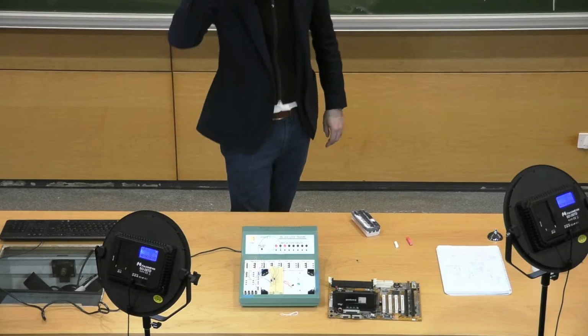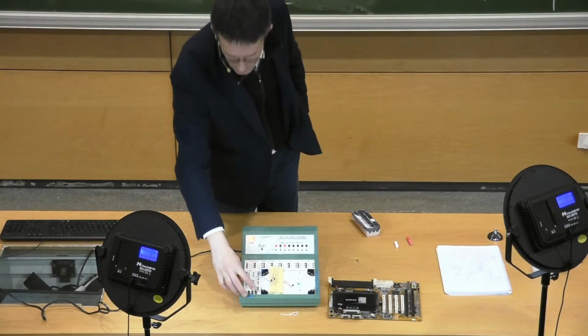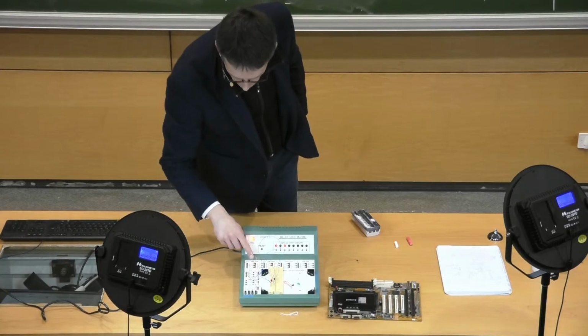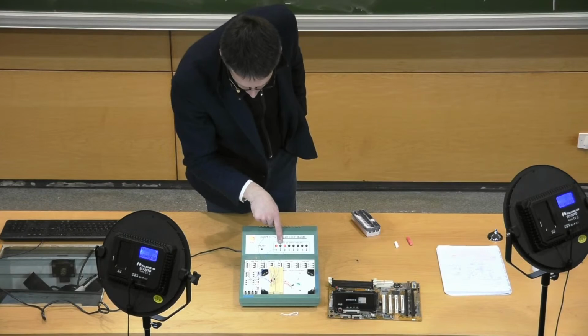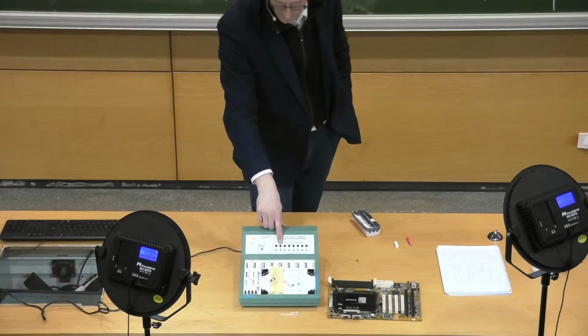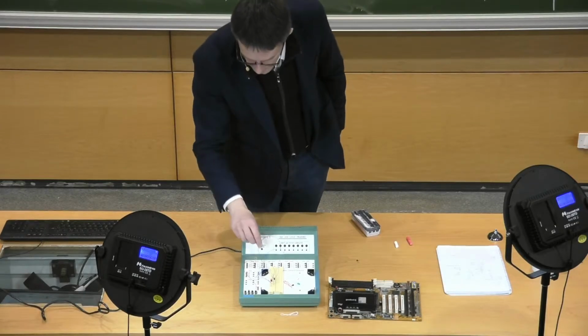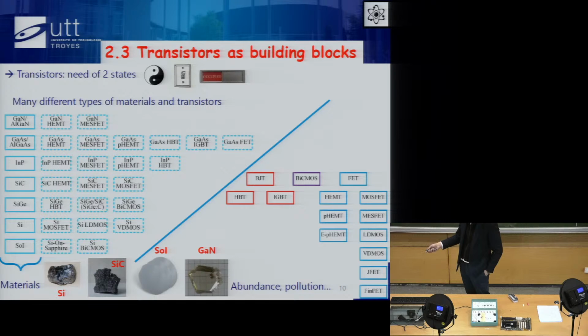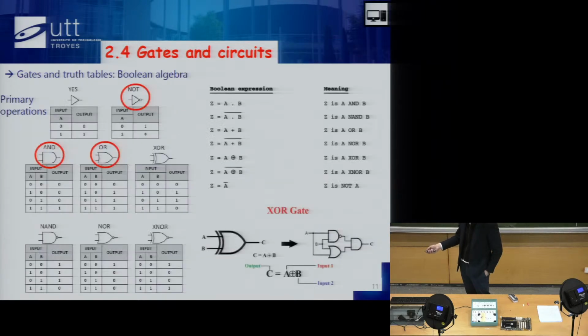Okay. You also have an example here. I've got these 2 switches, P0 and P1, linked to an AND gate. So now you have to look at this one here. I can switch that one, voila. Number 6 is basically the output of an AND gate. And you can see this one will be 0, 0, 0, unless the 2 switches are on at the same time.